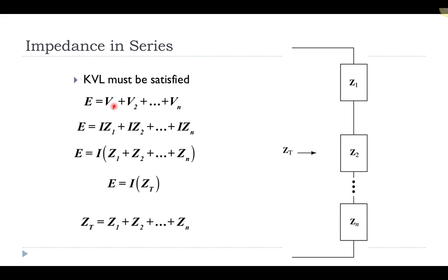According to the equivalent of Ohm's law for AC, the voltage across the first component is just the current times the impedance of that component, and the voltage across the second component is the current times its impedance, and so on, where all of these currents through components connected in series are exactly the same. There's no source connected here, but you have to imagine that there's some AC source connected here. There's only one loop possible, and so the current through all of those components is going to have to be